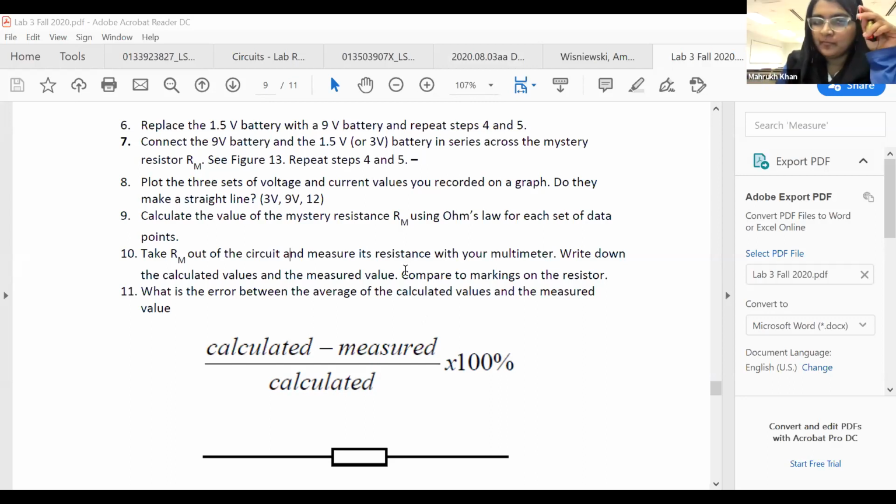Oh, because one thing can happen, okay? I'll show you. If you see these rails here, and if you connect these two wires, or somehow it may happen that this is your power rail, and by mistake you connect it to some wire that is shorted with this power rail, then the battery will be shorted and this will be melted.